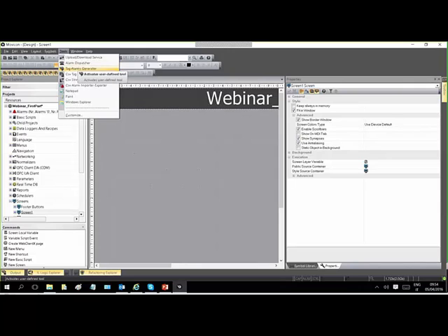At the end, to conclude with the workspace, here in the bottom part, we have the output windows. These read the logs that Movicon stores by default, so you have important information while you are debugging your project. These output windows will be available also in runtime through this flag.